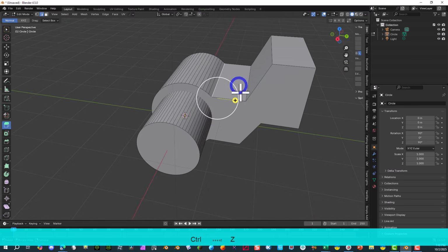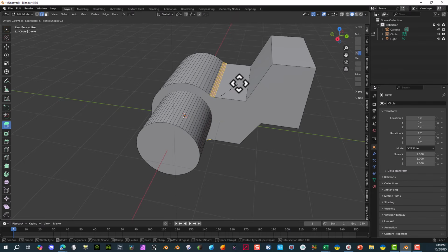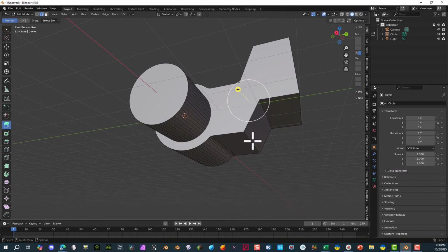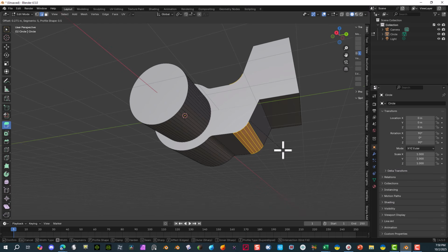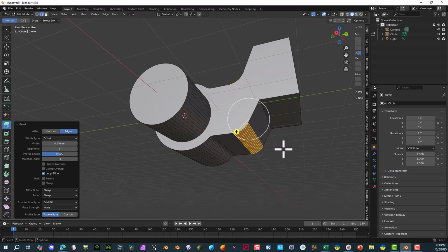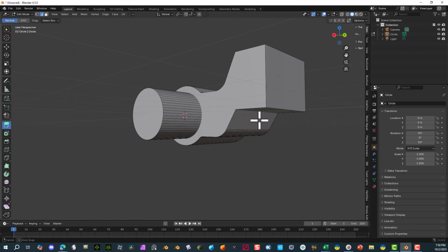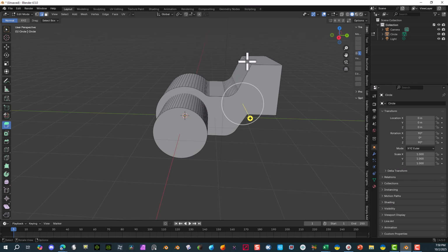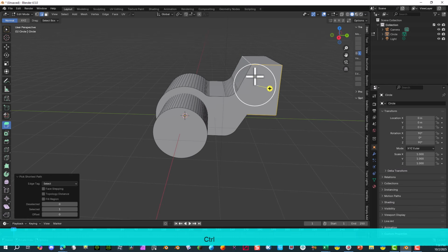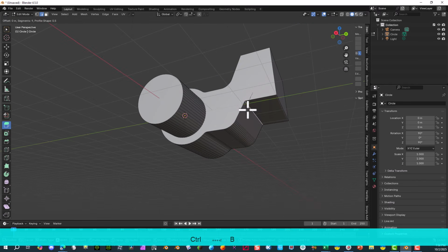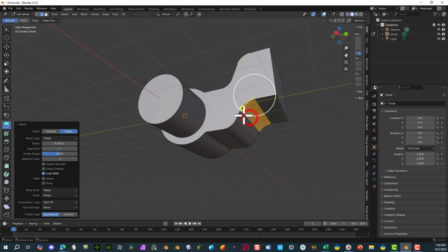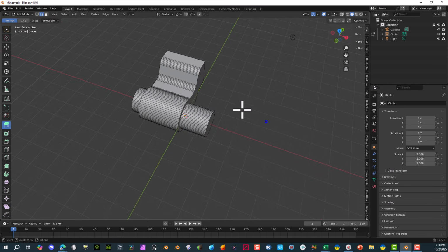Okay, so before we do anything, we're going to go in and do a nice bevel on this. So we're going to select those two edges and pull them out with Control B. And same thing here, Control B, and we're going to slide it out a little bit with so many faces. So here I did 9. And then we got this one on the bottom and the top. Select it with Shift. And again, we're going to go Control B. So pull this out. And we can keep the same. That's fine. Just giving it some nice curvature, basically.